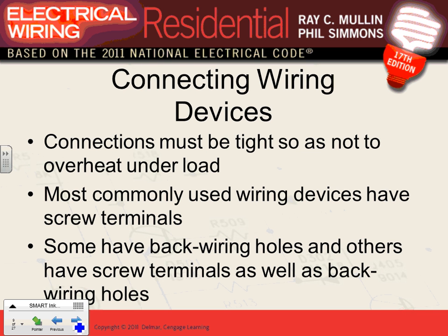Devices: they get this one in a master exam and journeyman exam. Everything has to be tight in electricity. When we torque, not over tight. We have foot-pound torque that we can torque all these lugs. So this connection must be tight for switches. If you don't tighten them, or you over torque them, what are you going to get? Overheat, right? Loose connection, overheat.